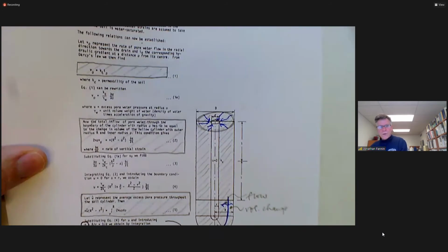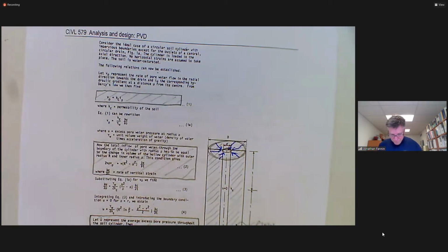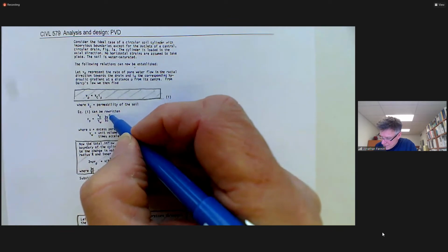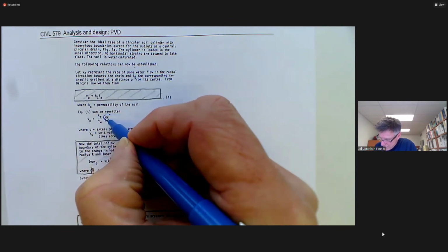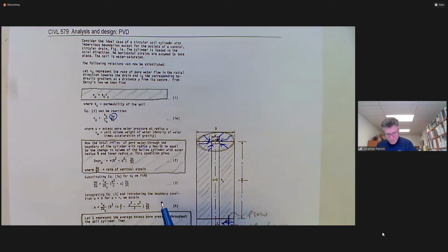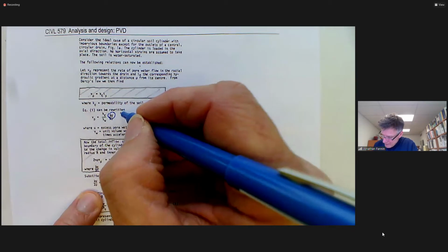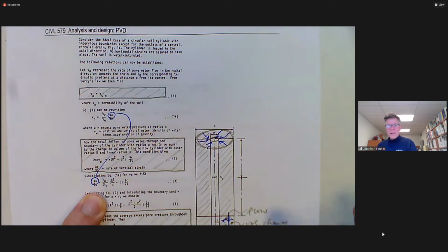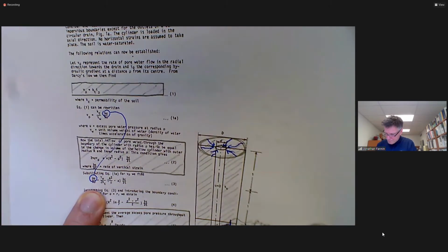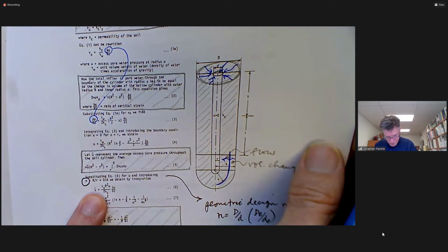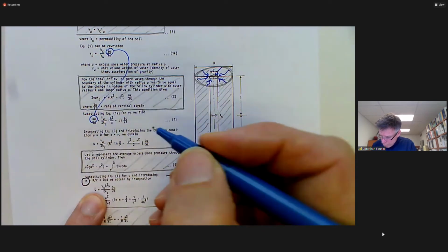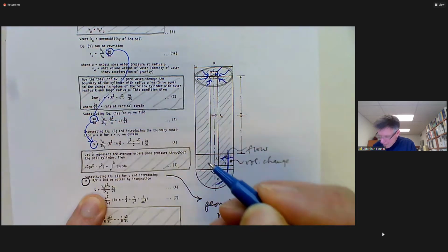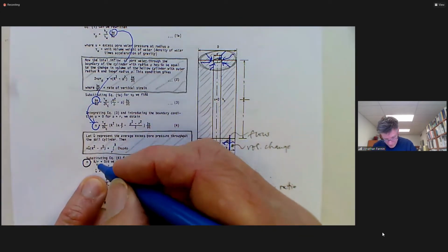Okay, now let's work our way through, and we start with the hydraulic gradient and a change or a difference in excess pore water pressure, delta U. And we can take that delta U and we take it down here and we continue to follow an expression for delta U, which we then relate to the excess pore water pressure U, and then the mean excess pore pressure U.